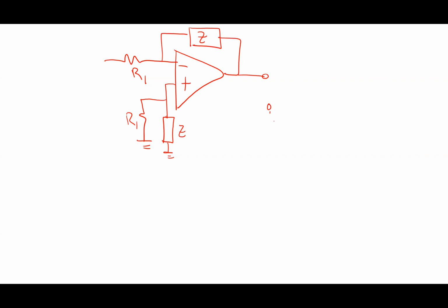And there we go. There you have it. This is V out 1, and this would be V1. I would do a KCL at this node. This is where you should be comfortable enough with circuit analysis to say, okay, I do a KCL at that node. I'm going to see that V out 1 is equal to negative Z over R1 times V1. Right? I would get that from doing the KCL right there. Questions about that? I'm not going to do the KCL.